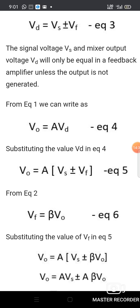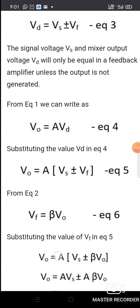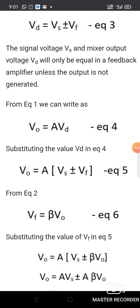We have the three equations from the amplifier's individual blocks. From the three equations we will get the overall gain of the feedback amplifier, not only the amplifier, right? For that we take equation 1. From equation 1 we can write V0 is equal to A Vd. Cross multiplication gives equation 4.